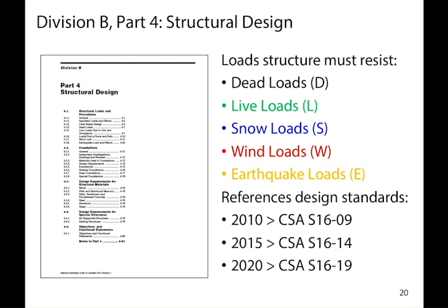And so the NBCC 2015 references the steel design standard called S16 from the year 2014. So right now in New Brunswick, you use NBCC 2015 and CSA S16-14. Some people use 15 with 19. Don't do that. Don't use 19 because 19 is formally withdrawn and you'll get in a lot of trouble for